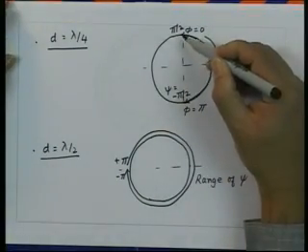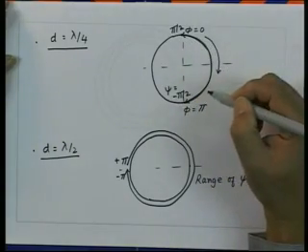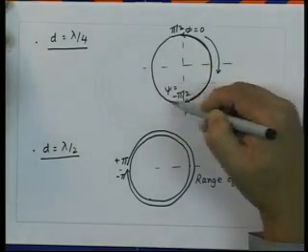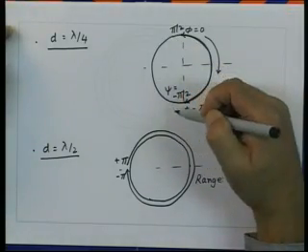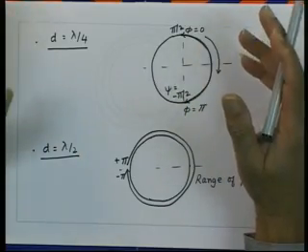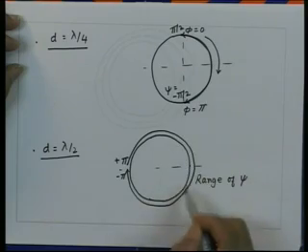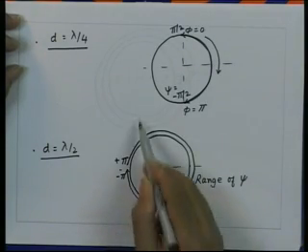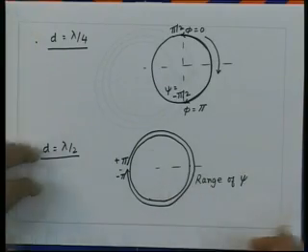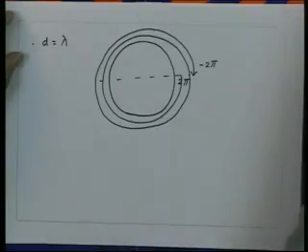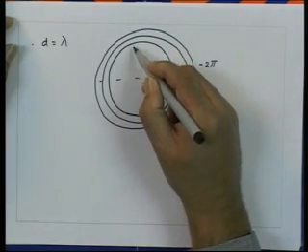So, now if I look at these three cases here, in this case what we see is that the total unit circle is not covered by the visible range of psi. So, we have a portion of the unit circle where if we put the roots of the polynomial, they do not affect the nulls of the radiation pattern. In this case, if we put nulls on the unit circle, they have corresponding directions for the nulls in the radiation pattern, and these are unique. However, in this case, if I consider a null, let us say somewhere here, it would correspond to two values of psi.